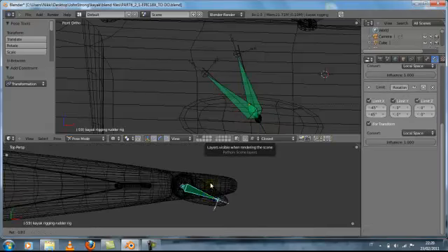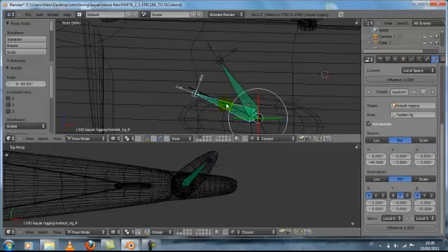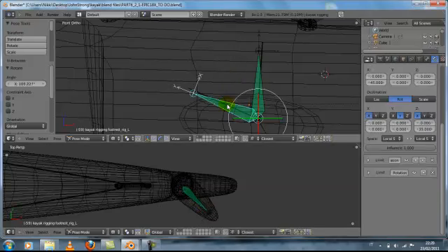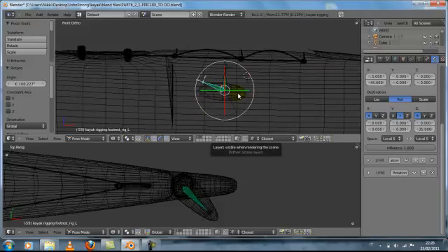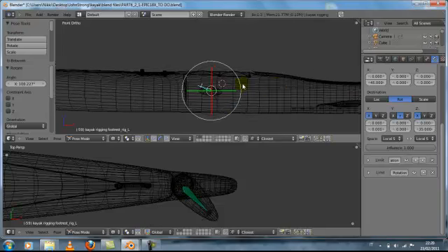Okay, now just test, rotate, and it works nice. So the rudder rotates to right, and the right footrest rotates, while when the rudder rotates to left, the left footrest rotates. So we have created the right rigging. But what we want to do is also to create a driver that can command the rudder movements and the footrest rotations.